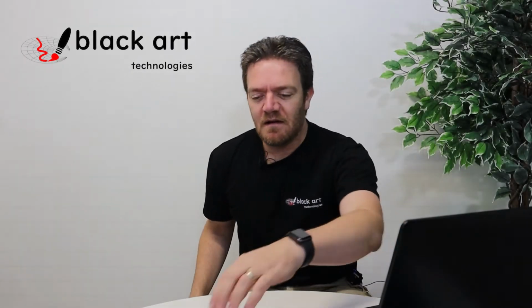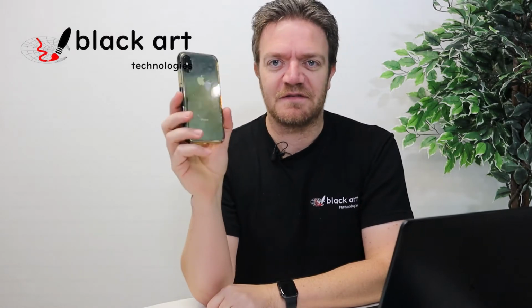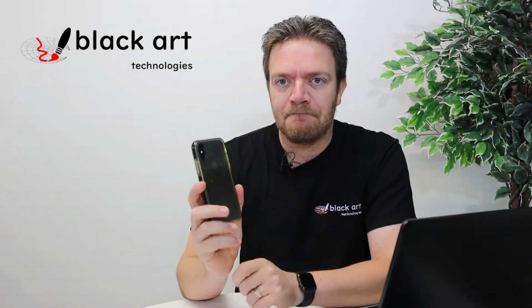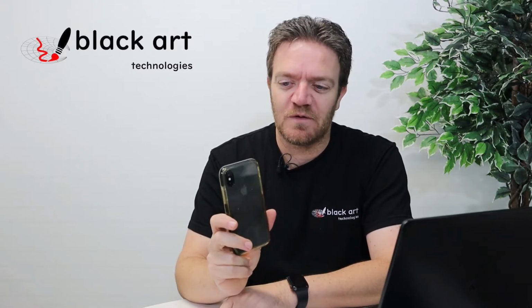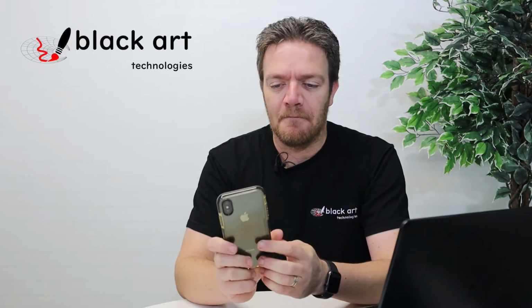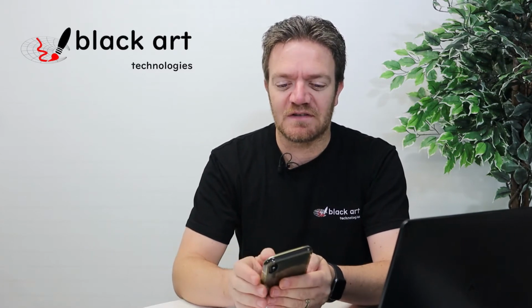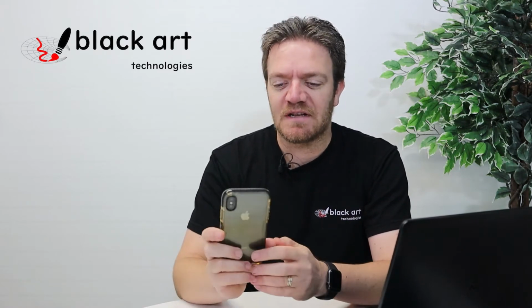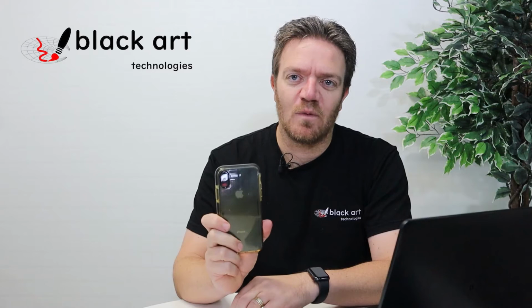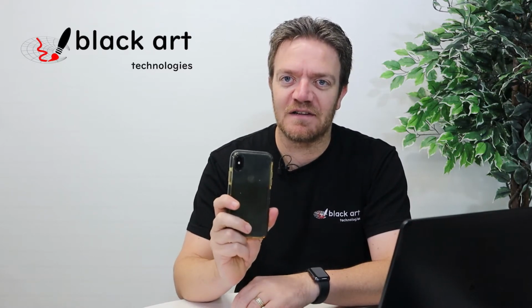Okay, I'm back. My phone, this is an iPhone 10, so I guess by now it actually feels like an old phone. It has GPS, it has 4G, and it covers all the Australian bands. So the 4G antenna is not just a silly little antenna, it's quite a complicated antenna. It can do MIMO, so there must be at least two 4G antennas of some sort. It has Bluetooth, so it must have a 2.4 gig antenna in there. It has Wi-Fi, dual band Wi-Fi. So there must be a dual band 2.4 and a 5.8 gig antenna in this phone.